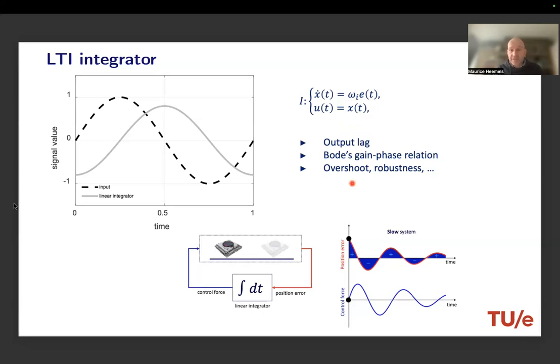The reason is that you have phases of time where, for instance, the error is positive, but the integrator is negative, so it's pushing essentially in the wrong direction. There are moments when the integrator is really making things worse performance-wise. The error is positive, and the integrator is pushing in the wrong direction. It makes the error even bigger for a while, simply because it's pushing in the wrong direction. So the sign of input and output are not equal.